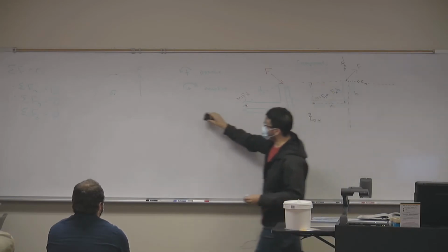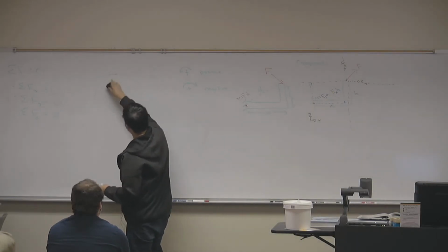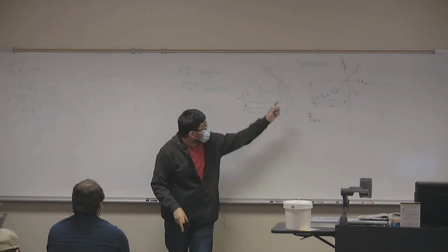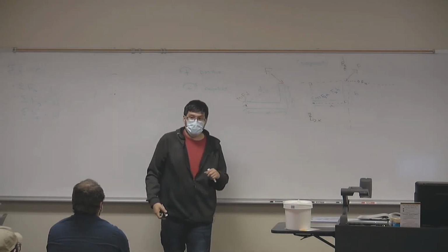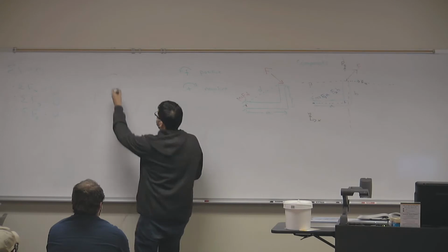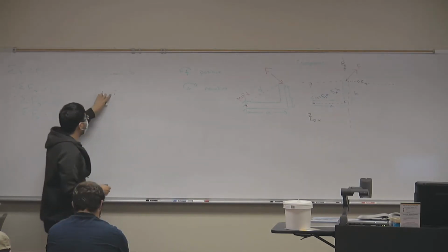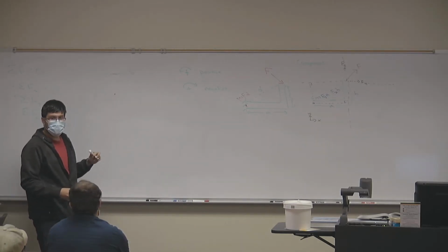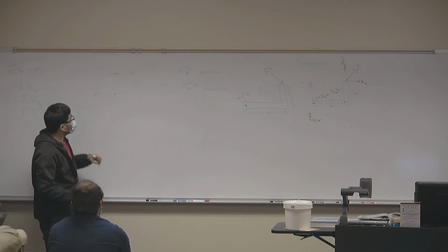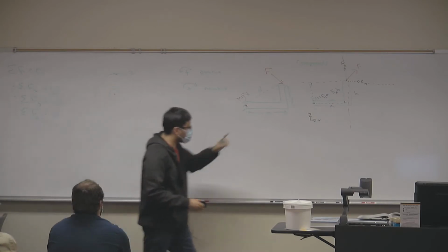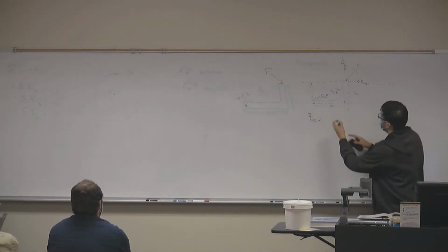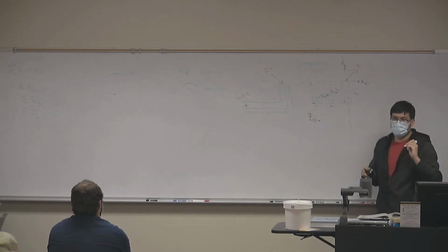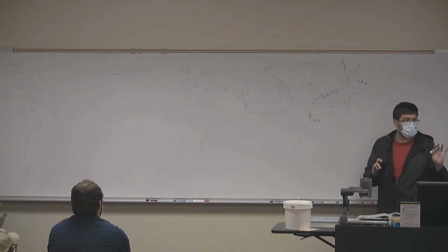That means that I have a force applied on the top of my steering wheel in which direction, left or right? My x direction. That'd be to the right. To the right, okay. So in which direction am I rotating the steering wheel now? Negative. That's right, in the clockwise or negative direction. That means that my x component of the moment will be negative. Does that make sense so far?